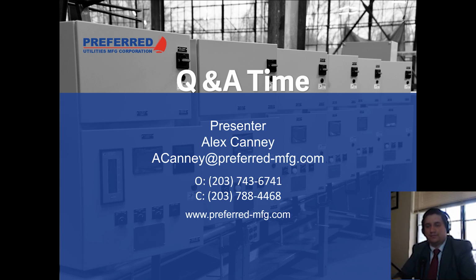Another question in the chat is, what's the typical communication protocol provided with your PLC controls or FSC controller? So we have Modbus on our tank gauge, Modbus on our standard transfer pump set, which is typically the traditional heart of the control system for a fuel oil system like this, and then BACnet as well. It's BACnet IP, so you can just plug an Ethernet cable into the back of our 4-inch OIT or 10-inch, depending on the size of the system. So that usually covers us. Once in a while, we run into BACnet MSTP. That can usually be handled with a converter, either on our end or the building automation end. But most of the time, we're going to be covered with either Modbus or BACnet.